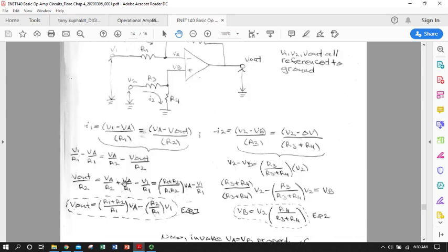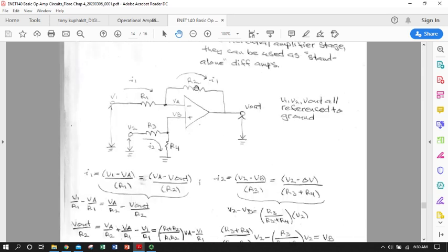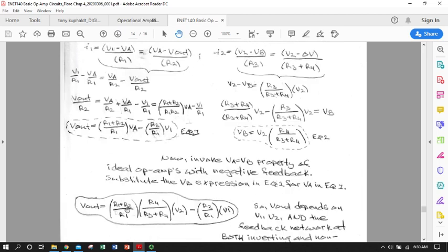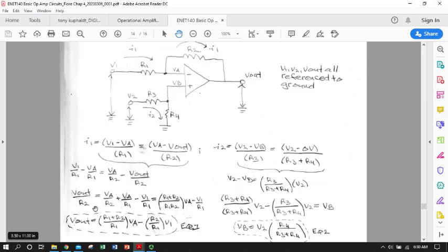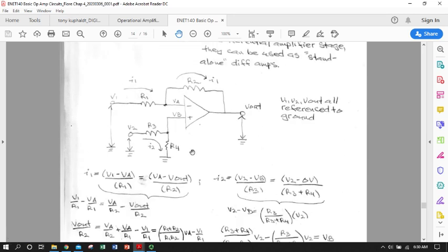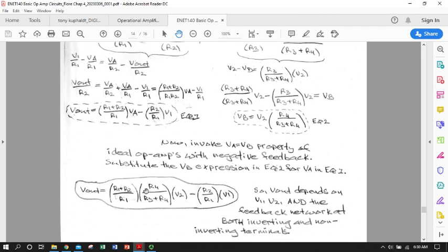So the R's are things that you'll design in a circuit. Your feedback resistor, your inverting terminal input, the voltage divider for your non-inverting signal. You're going to presumably know what your input signals are, and this tells you what you expect for your output based on your inputs. Let's see if some things make sense.